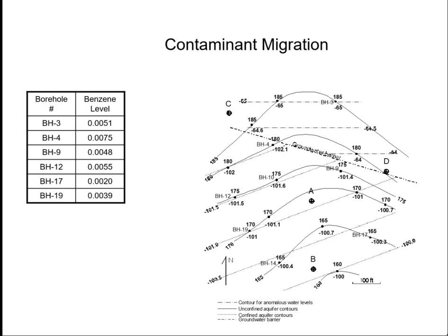Contaminants, which is what this problem is about, depths of things, it's all the same thing. You're connecting points of equal value and bracketing points of like values. So when I take the data that's given here, I've got 6 boreholes. There are far more boreholes than there are listed. And all that may mean is that the water wasn't tested there, or they sealed the upper aquifer and they have been using only the lower aquifer. So since this is a contaminant that's at the surface, then the lower aquifer has no contaminants in it.